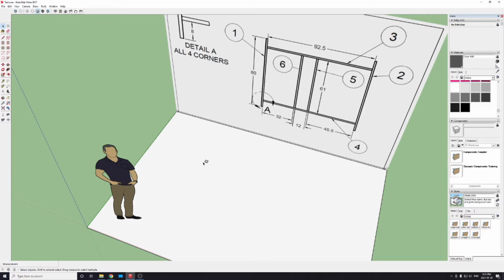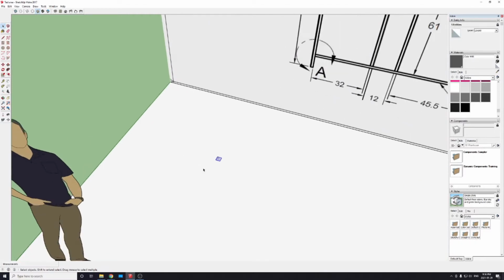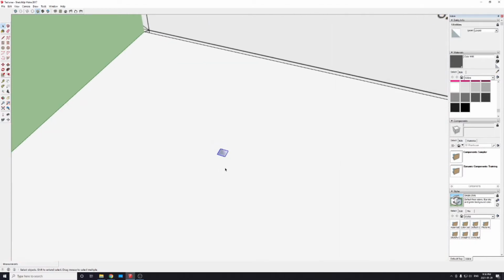So I'm going to hit spacebar to clear this selection. I'm going to left click a box around this square, and I'm going to hit M for move. And you notice I have not made this into a group yet. We kind of did that on purpose. So left click, M for move, and I'm going to move this over. Remember, if we hit Control, it will create a copy. If I hit Control again, instead of making a copy, it'll just move it.